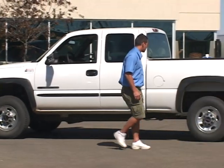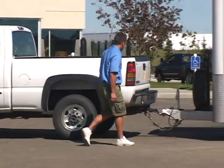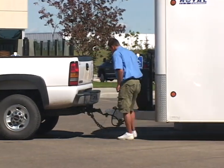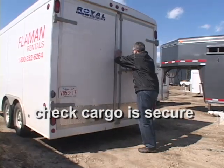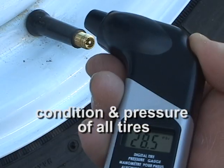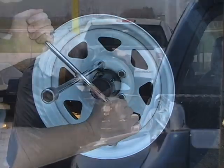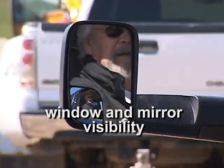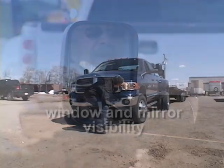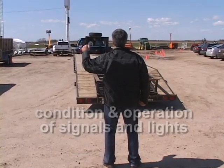Prior to your trip, always do a walk-around to make sure the vehicle and trailer are in safe operating condition. Inspect the following. Check your load is secure. Check condition of tires on the tow vehicle and trailer. Check wheel nut torque. Check window and mirror visibility. Check condition and operation of signals and operating lights.